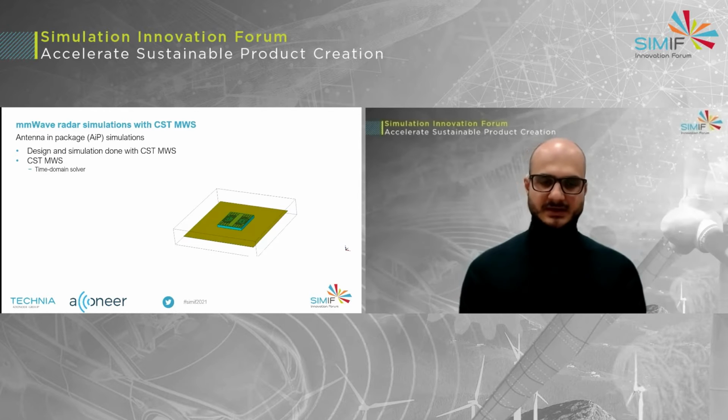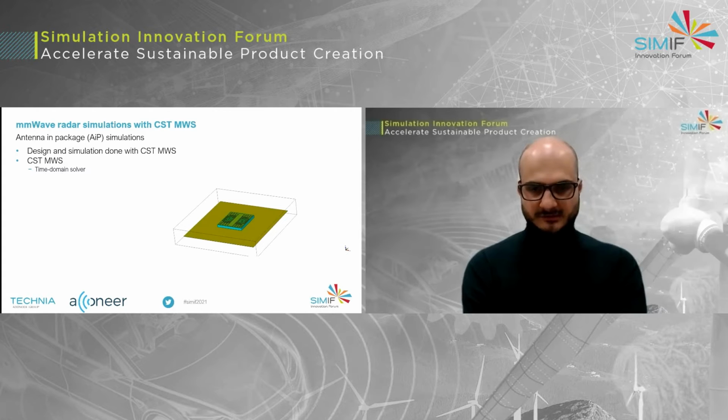So in terms of environment, in CST MWS Studio, specifically for design and simulation of the antenna package, we use the time domain solver. I will talk about the main advantage of using a time domain solver for the pulse coherent radar.